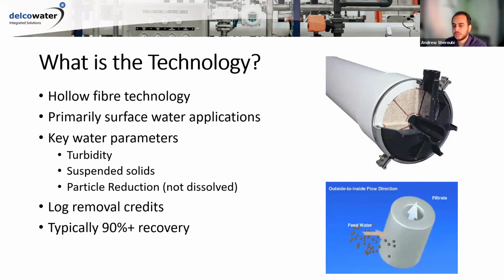There are different ways to do ultrafiltration, but again, with this hollow fiber method, you have basically thousands of these, let's call them spaghetti strands. So imagine a tube with thousands of spaghetti strands that are hollow. Water goes around those tubes, and then you pressurize it. Feed water goes through to the middle and captures the contaminants on the outside. You can also have what's called inside-in, so water flows in the middle of the tubes, and then it gets captured in the center.